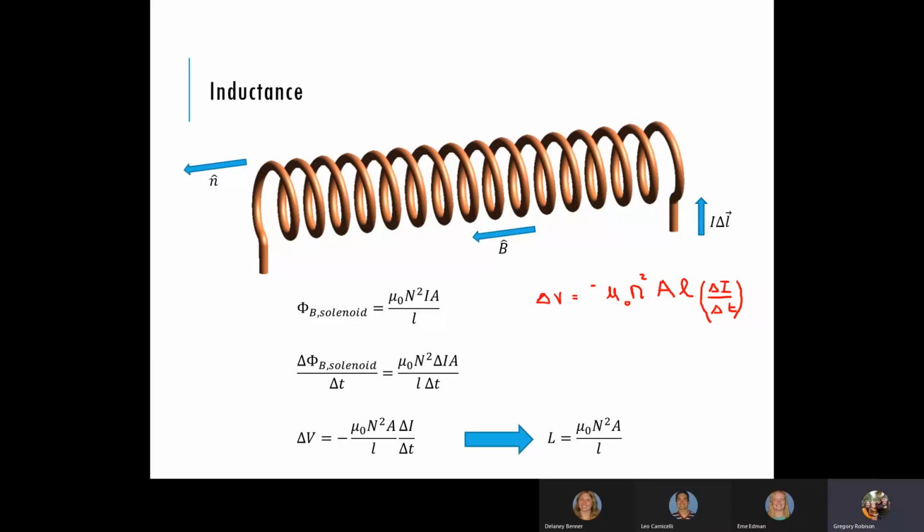And yes, that also, I think we talked about clean power and dirty power, right? Like the orange versus the gray plugs in the walls that you see. The gray plugs have dirty power. There's a little bit more variation in the current that comes out of those plugs, whereas the orange ones, a little less variation. They're more steady. Okay. Well, one way that you can try to take care of those slight variations is put an inductor in the line. The inductor will, again, try to smooth out any rapid changes in the current. It'll filter out some of the noise, some of the dirty power.